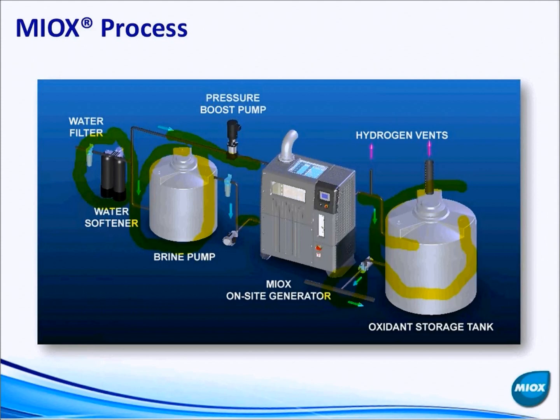So in the case of drinking water, for example, you may have two pumps in this location. One might be for pre-treatment prior to a filter, for example, and then another may be used for final disinfection prior to your clear well or your distribution and storage system. So very simple process flow. The only consumable that you're using in this case is food-grade salt. Systems are NSF approved as long as you use NSF salt. So if you use food-grade salt and put that in the system, then the system is applicable for NSF approval.